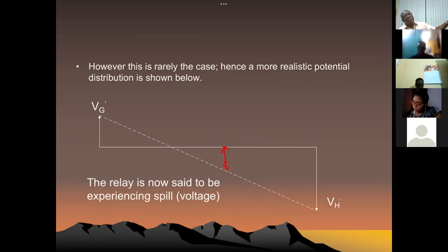And we looked at this earlier when we were looking at the transient response of your CTs. We said that that was dependent on the ratio of the inductance to the resistance, or the X to R ratio. So the more concerning phenomenon would be what happens under transient operation. What happens when we have larger currents flowing through the CT?